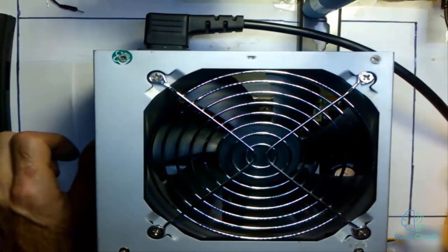Therefore, the test lamp allows you to connect a power supply to electricity without any risk. And if you see that connecting a power supply to the test lamp causes the lamp to light up, that power supply has an internal short circuit, and if you plug it directly into the electricity, the circuit breaker will trip. But if you see that the lamp does not light up, it means the power supply does not have a short circuit and you can work on it more easily.